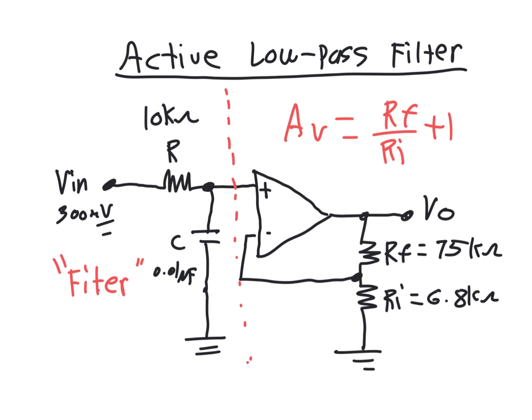The advantage of using the op-amp, as we know, is that the input impedance is essentially infinite. So the op-amp draws practically no current, so it doesn't load down the filter. This is a really great advantage because if you were trying to drive the next circuit stage with the filter directly, its characteristics would load it down. So the op-amp essentially makes the filter behave more ideal. So that's a good situation.